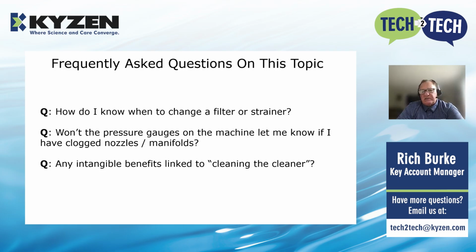Won't pressure gauges on the machine let me know if I have a clogged nozzle or manifold? So, a great question, and unfortunately, in most cases, no, it will not. In fact, it may actually give you a false feeling of security. So think about it: the pressure gauge sits between the pump and the spray manifold, so in between that line. So if I have a clogged nozzle or clogged nozzles and manifolds, the pressure actually stays the same or increases. It doesn't decrease.